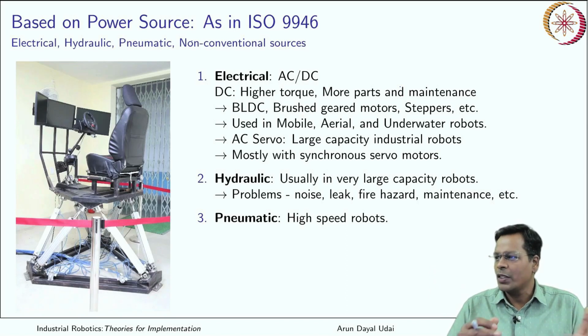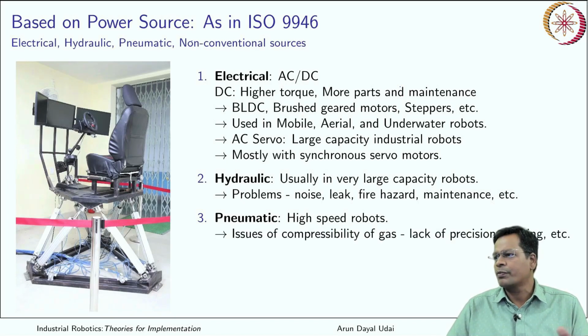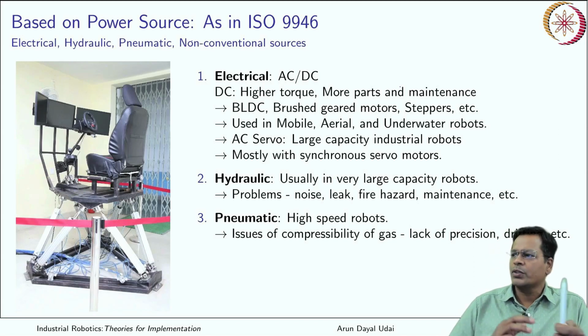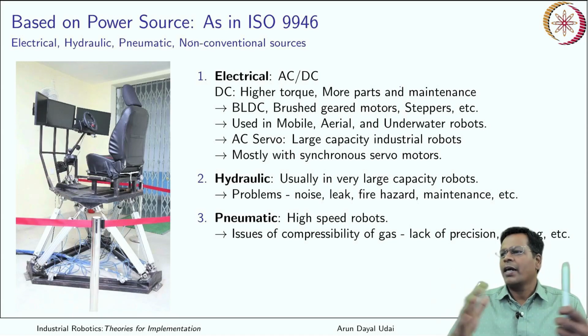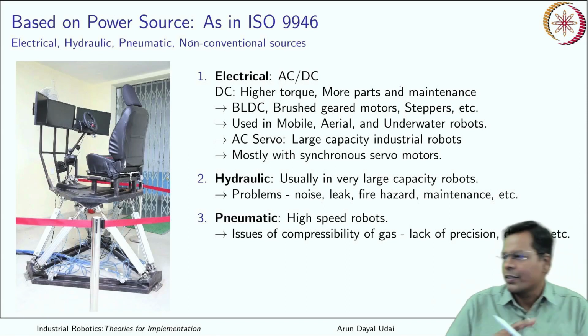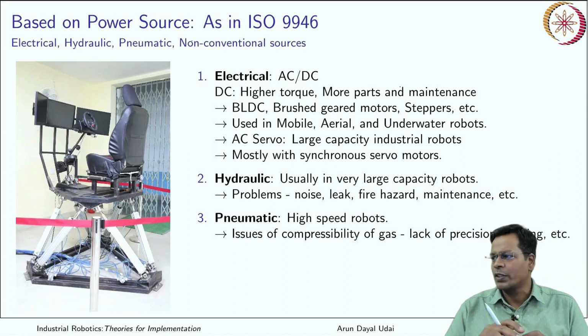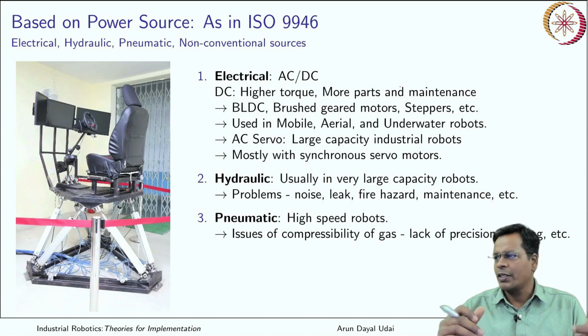And you see this kind of robot can also work, but the only thing is you have to be a bit careful because air is compressible in nature. Because of compressibility, it loses some sort of precision, and with an increase in temperature, the air can expand, no? That will create some sort of drift, and those are the related issues with this kind of robot. So yes, pneumatic robots are there. Okay.